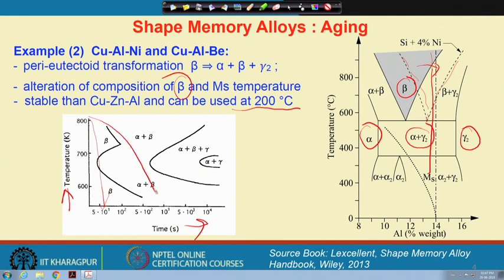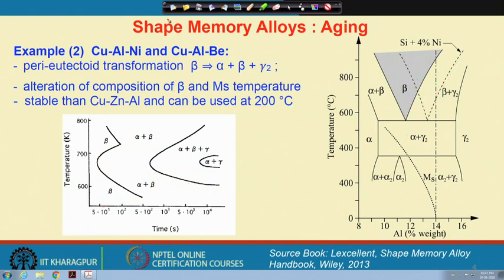However, with slower cooling or a little bit of diffusion, if we allow, you can start from here also, then with time we can decompose into alpha beta, or let us say alpha beta gamma and so on. So, this is basically the understanding we really need, how to get back or how to make these reversible transformations in such a way that no competing phase will appear in between a phase transformation sequence of martensite and austenite.